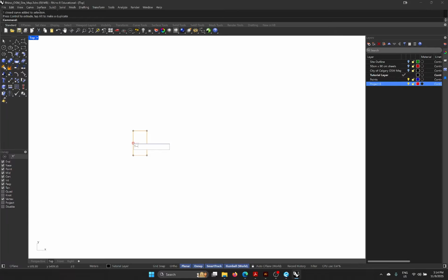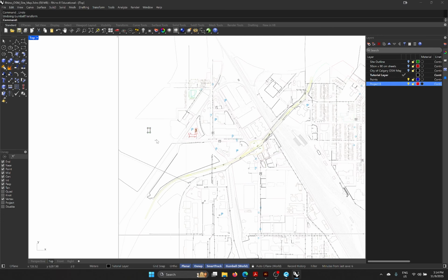So I'm going to scale this by 100, and I'm going to hold shift as I click on this little box in order to do this. So you click on it, click on the box, type in 100, hold shift, enter, oops, hold shift as you're clicking the box. There you go.